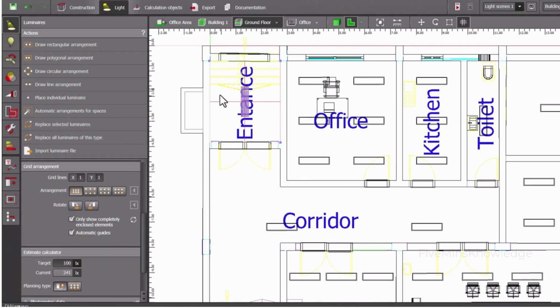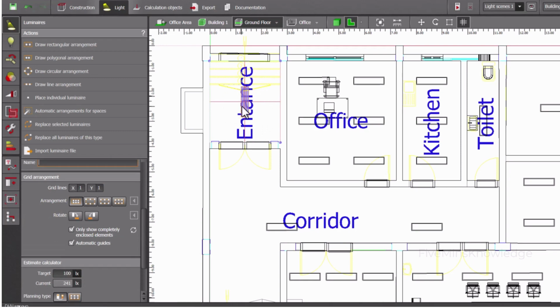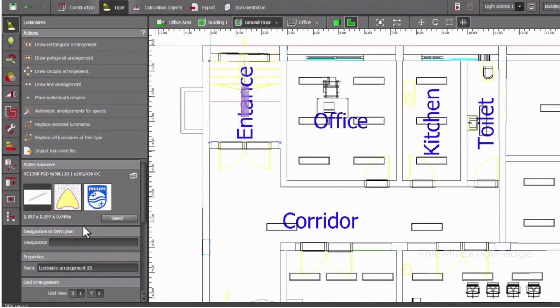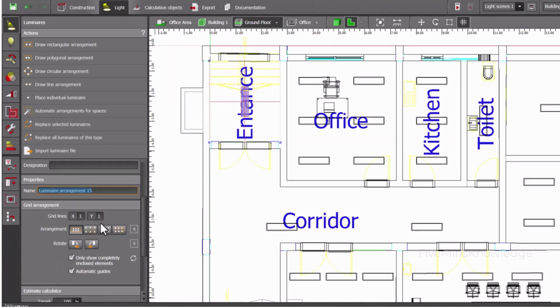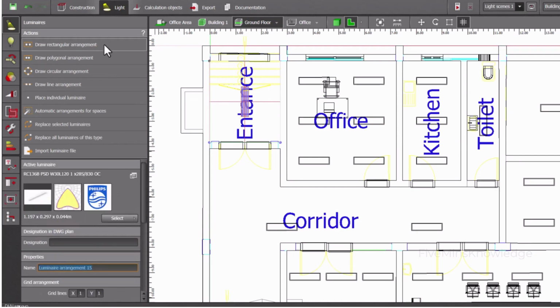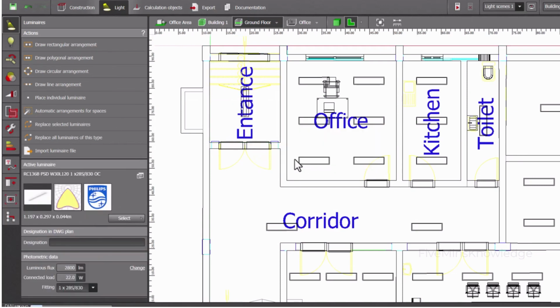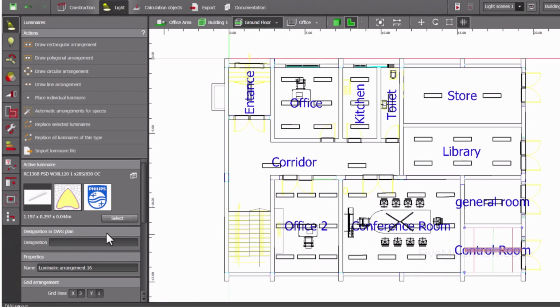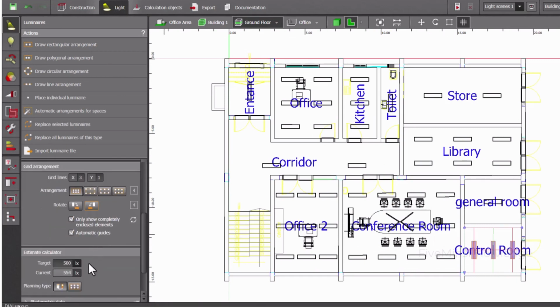It still has far more than our requirement, so delete this. Okay, let's keep it here and we'll see the result. Then we will look into the error later. It is having far more than the required lux. So let's install. This is almost matching our required lux.